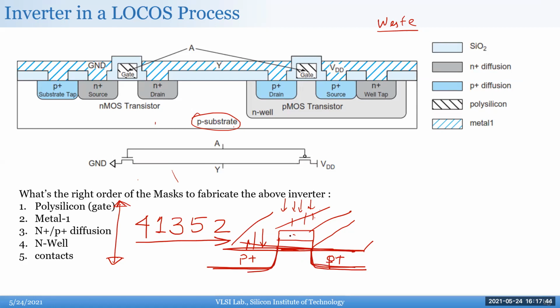If you did this, the poly would be shifted this way or that way, and you'd basically get an open device. That's how they did it in older technology, but that was like 10 micron devices. Now they are 2 nanometer devices. So you're talking about like 6 orders of magnitude. So that's where the self-align helps you. So everyone is clear with this, right?